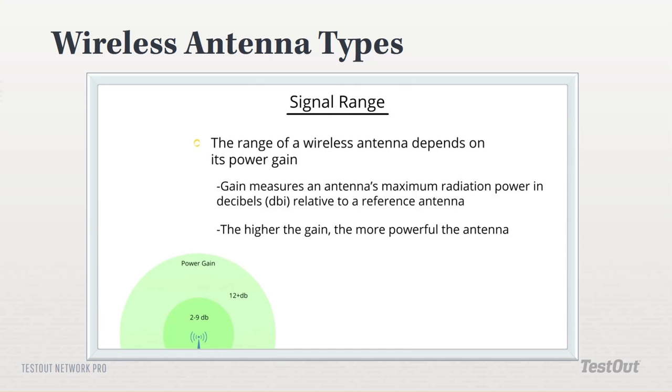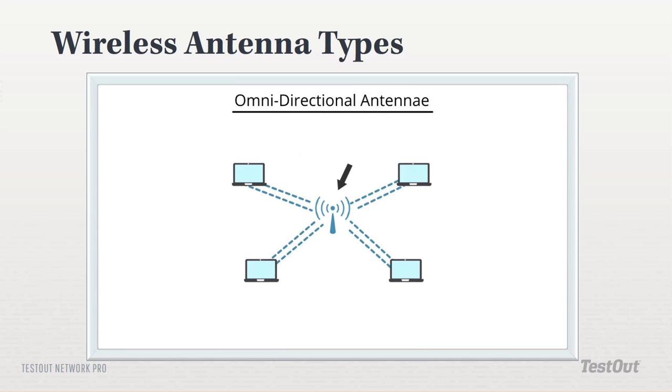You don't want something traveling very far outside your building where other people can use packet sniffers or something like that. So basically, if something's 50 meters apart, then you don't want to use a low gain antenna. You really need to blast the signal between the 2 points, assuming you're using antennas there. Omnidirectional spreads it out in all areas.